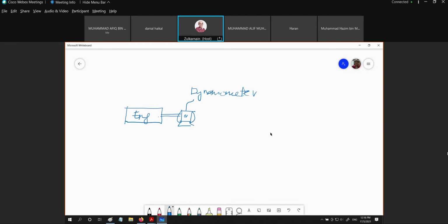What we have from the dynamometer, if we look at the side view of this dynamometer, basically has a torque arm and we have a spring constant which is anchored to the floor. And this torque arm usually is the torque that we could have, the value of this force which is perpendicular to the center of the dynamometer. Okay? So if we have this R value, then what we could measure right here is the spring constant, and the spring will give deflection because of the engine. And this will be calculated by using K times X.